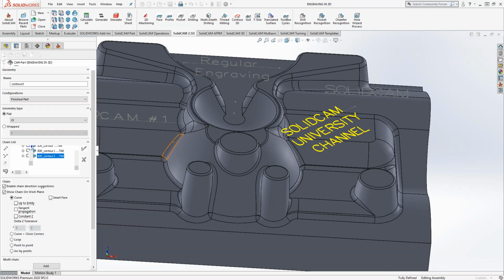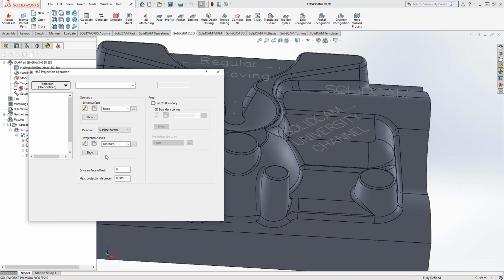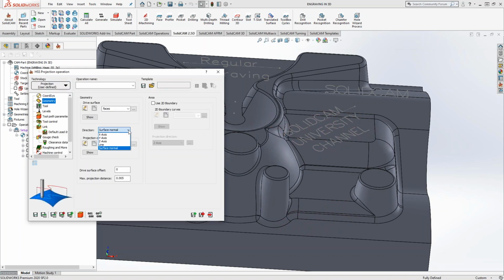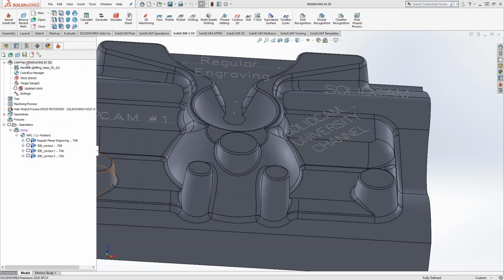Now this is going to do the exact same thing as the 3D engraving, but when you get into the 5-axis, under the tool control in the 5-axis section, what you can do in there is tell it, maybe I want to keep it concentric within 45 degrees. So my 5-axis machine can actually rotate around within that 45 degrees cone angle. So to answer your question, give it a try. Yes, absolutely, let's go in there.